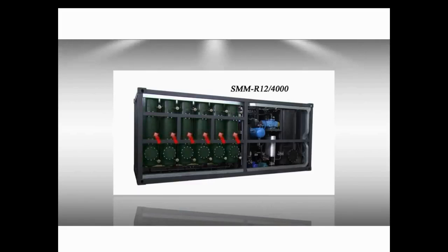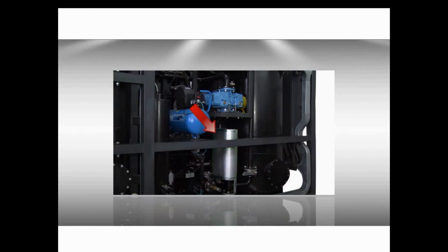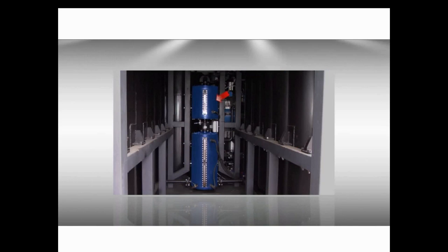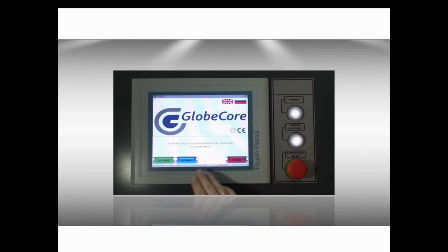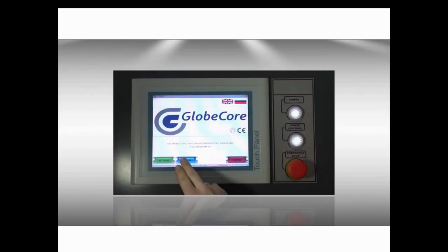This is a typical GlobeCore plant. It's a full regeneration plant with vacuum degasser, Fuller's earth section and computer control. If you want, you can just use a degasser for oil purification or combine it with Fuller's earth. For example, you come to a substation where one transformer needs only oil purification while another one needs both purification and regeneration. To do all this work, you need the same machine and only one operator.